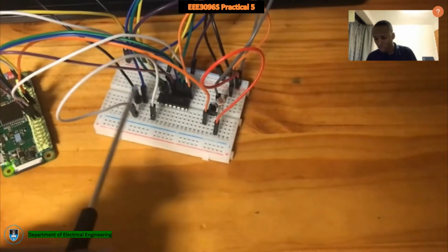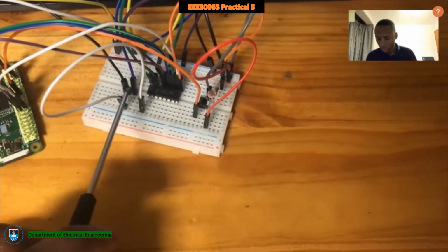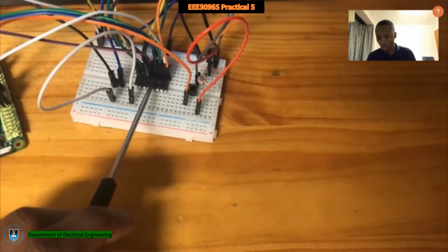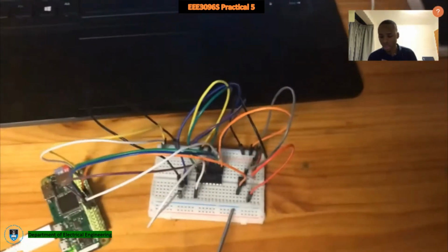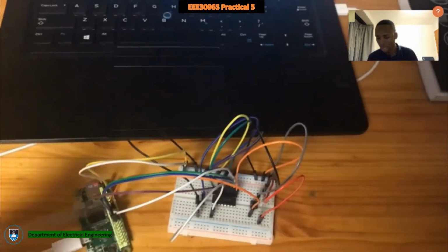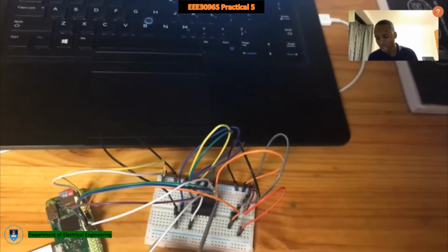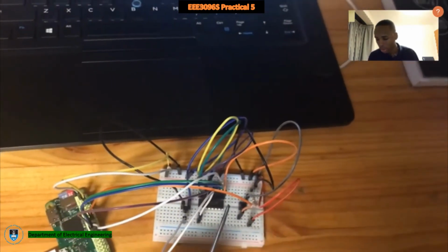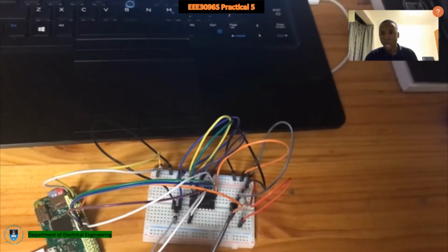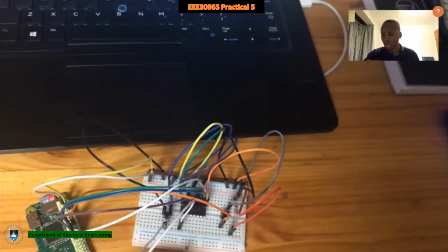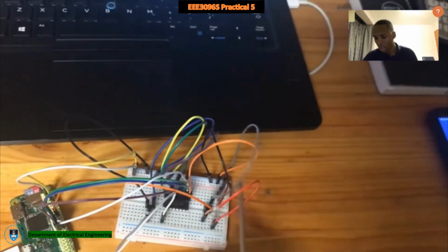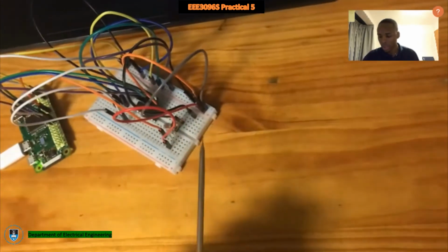So we have over here our thermistor and also our ADC chip. You'll also realize that we're using these terms interchangeably. It's an MCP3008 or just simply an ADC. And we also have our push button. So we can say this is our primary circuit or our actual circuit, and then on this other side we have our secondary circuit that has the LDR with a resistor.